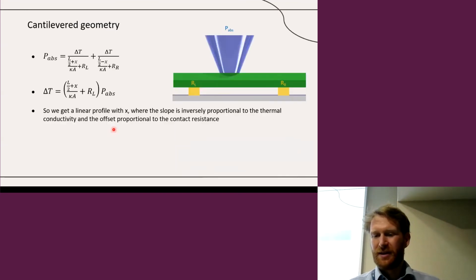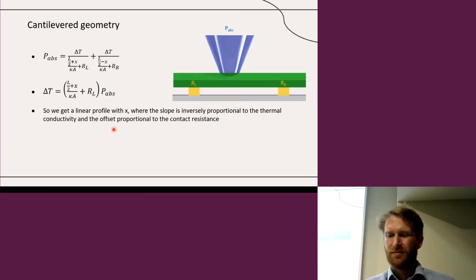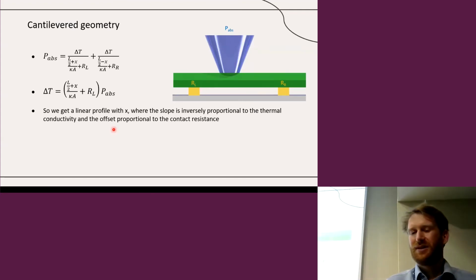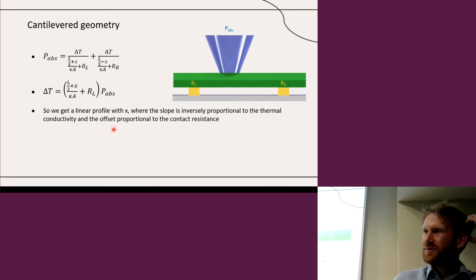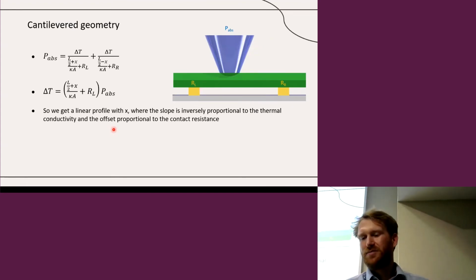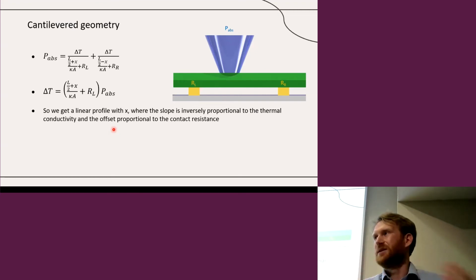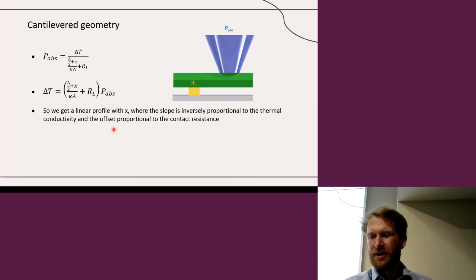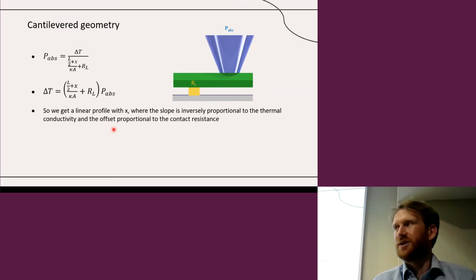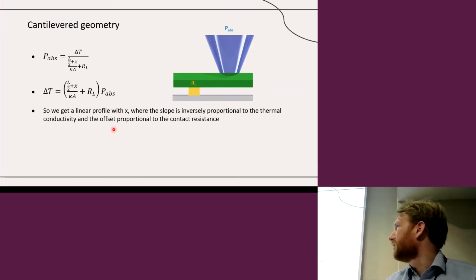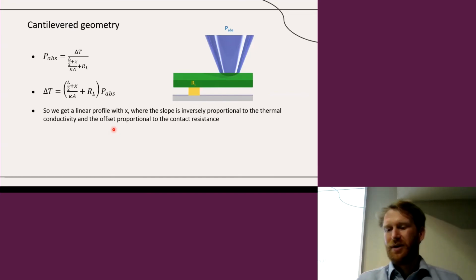One way that you can overcome the problem of the contact resistance, of course, you can model it with this more advanced model, but as pointed out before, since the effect is comparable, there are series resistance, it can be difficult to extract the 2 parameters independently. However, if we slightly change our geometry and we only use 1 contact rather than 2, and we move our probe,